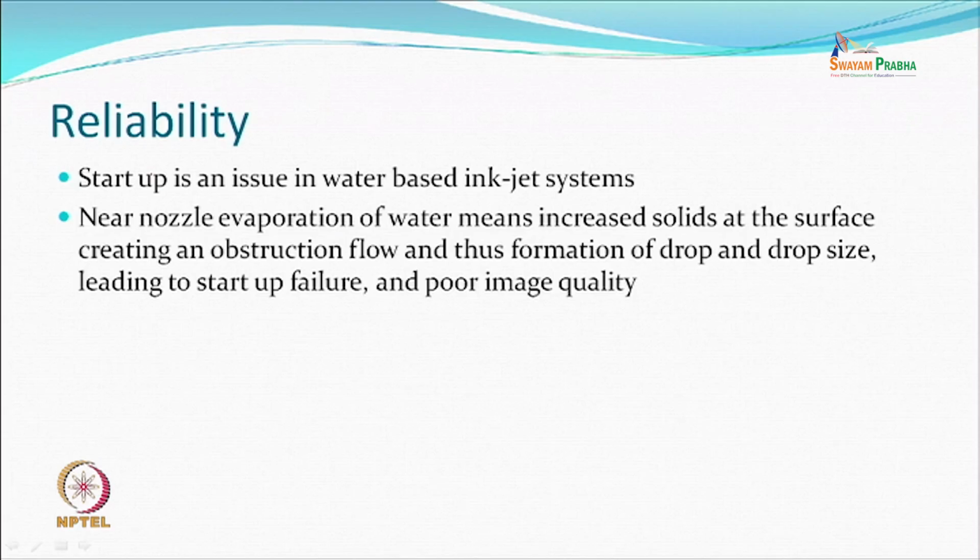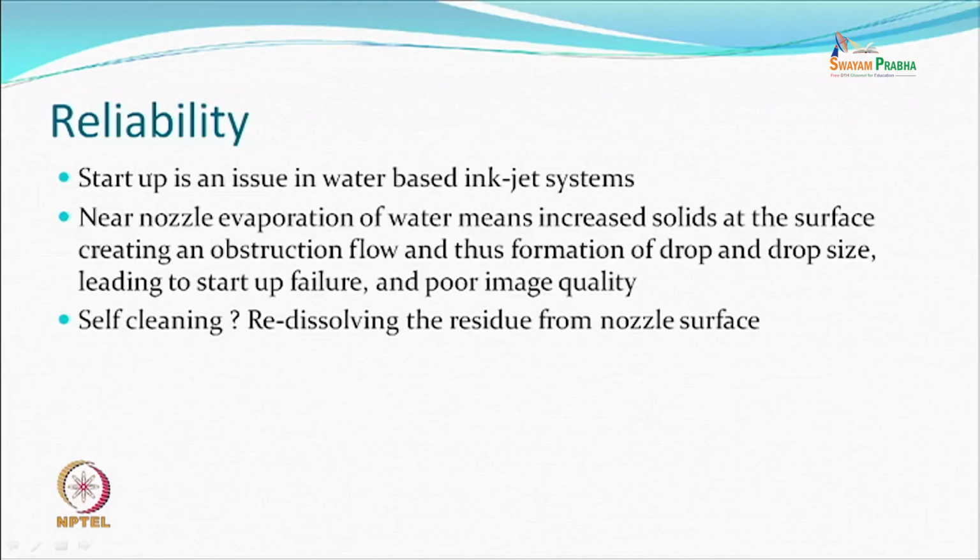Other than that, of course, you can have precipitation, coagulation, the dispersion breaking, that's a different type of story, then things will be very different. So, there's something called self-cleaning. Self-cleaning means redissolving of the residues from the nozzle surface by itself. And how will it happen? It would happen if you add some solvents which help it to get into the solution form.